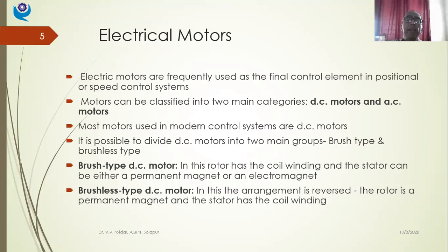Now whatever this control ring is there, the angular position of the control ring is controlled through a hydraulic servo mechanism or an electric servo mechanism. What I want to do is change the angle of the vanes of the reaction ring, the angular position. Earlier it was 30 degree, I want to make it 38 degree, right? So I want to change the angular position of the vanes of that control ring. So such a system is called a servo mechanism. There I make use of hydraulic systems, sometimes pneumatic systems, mostly electrical systems.